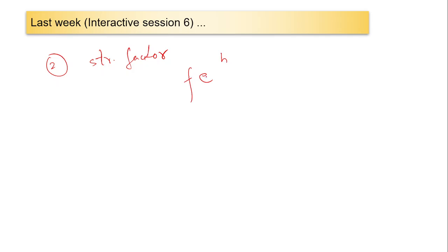That's why sometimes it is a little difficult to do XRD on lighter atoms. I mean, the diffraction or the intensity is less. Apart from the form factor, we have e to the power minus i, and then hx plus ky plus lz. This kind of formula is there. xyz is the position of the atoms in the unit cell, and hkl is that particular plane.